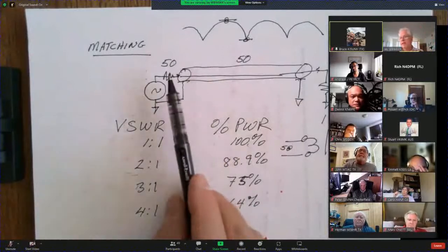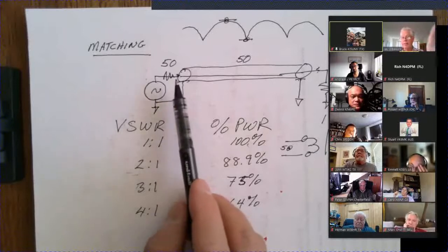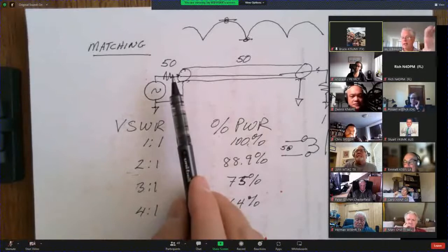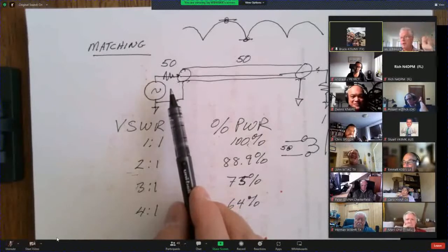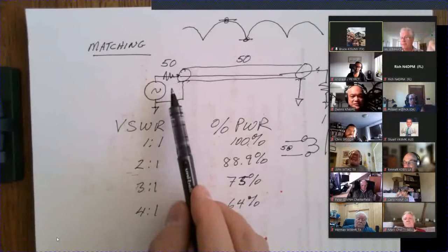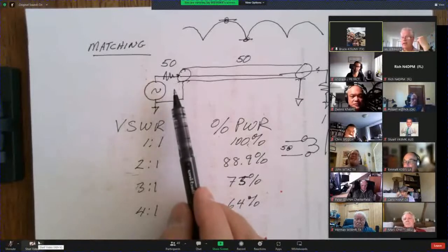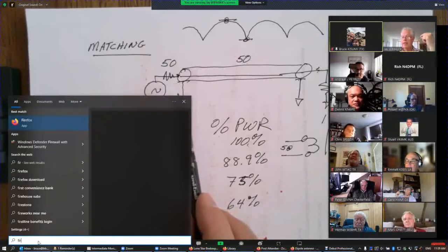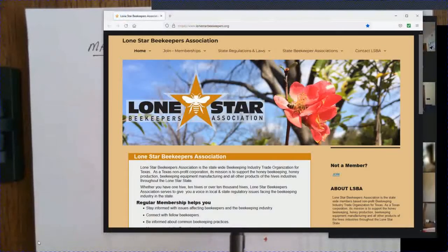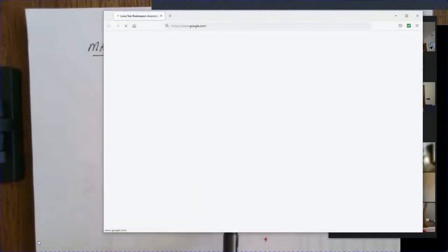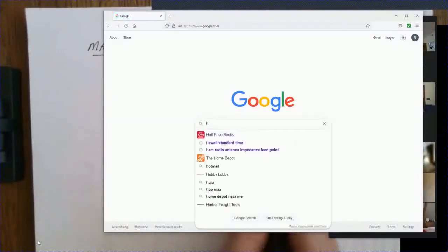One thing that you will definitely avoid is this: modern solid-state transmitters have safety circuits in them. They will say, look, I'm going to save myself. You can't match your antenna, but I am not going to die because of it. So I'm going to turn down my power so that I don't see 800 watts coming flying back at me. And so you end up lowering your power that way. Essentially, with 2 to 1, you could probably get away with a tuner, and you might get a little more power down here. Again, it depends a lot on the cable, its length, and everything like that.